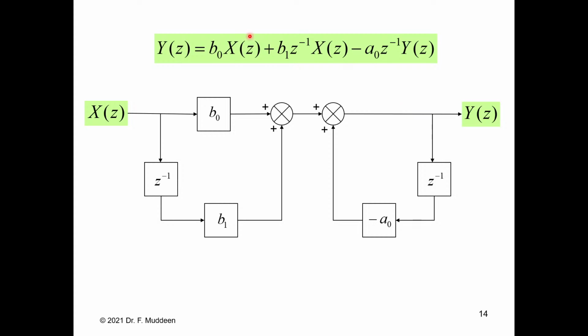And then these two parts here, which are added by this summation series being our inputs, need to also add to our first delay level of y of z here. So this goes to another summation point here. We already have factored in our minus a0 as the multiplication factor, so this can just go straight as a positive summation. And then the addition of all these factors here as a result from these summation points formulate our y of z equation.